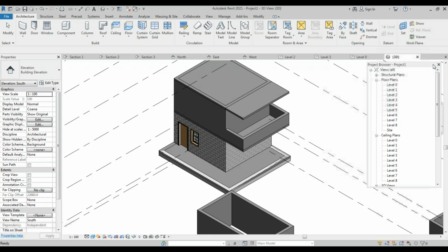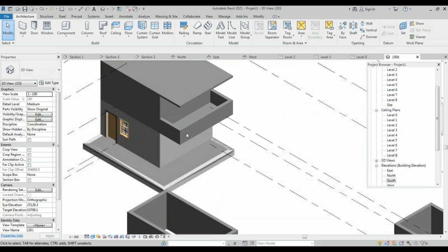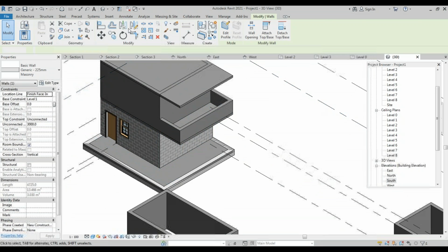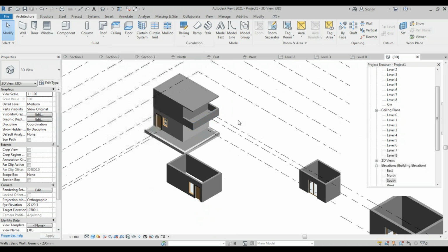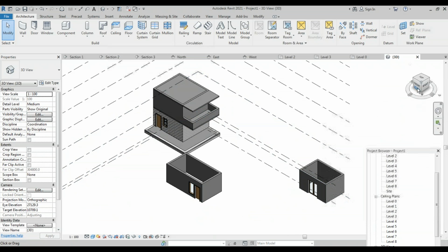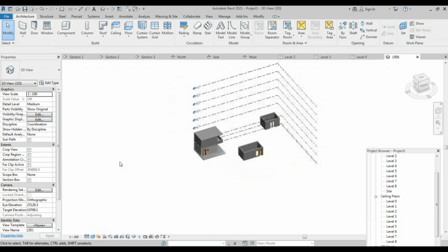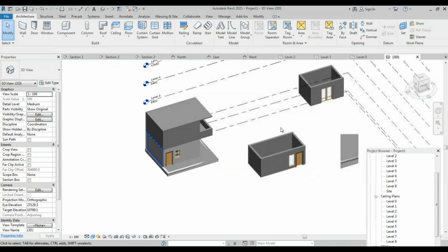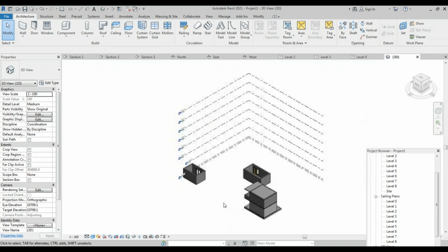No answers. Okay. So I think whatever I have to show you today with regards to Revit, I have shown you: the wall elevation, how to get 3D, how to get wall elevation, section and 3D. All the three things I've shown. You can also rotate this 3D over here and see how the building is. You can see what is behind. You can just click here, it will turn. Click here, it will show it from top.